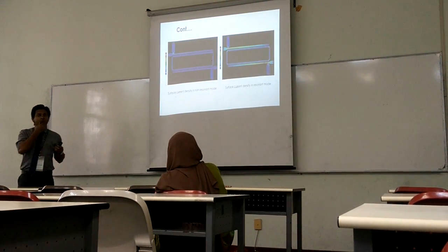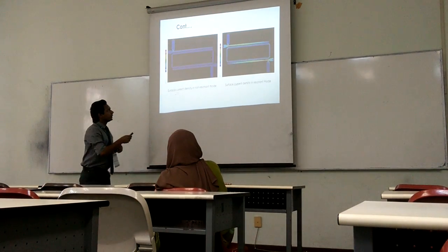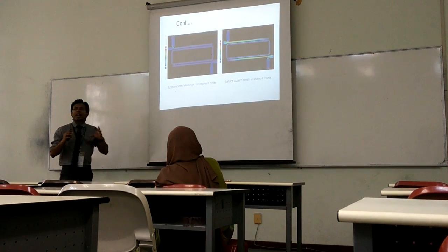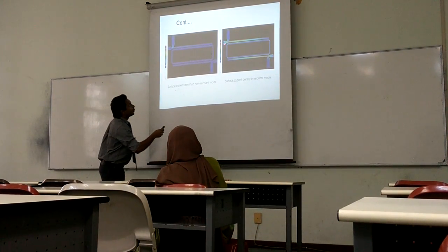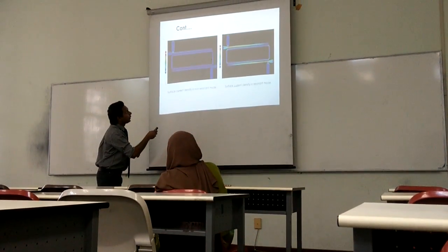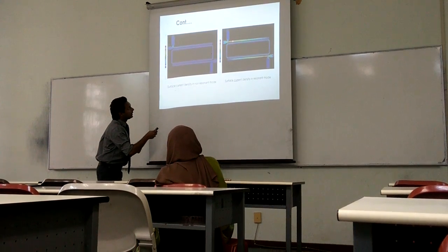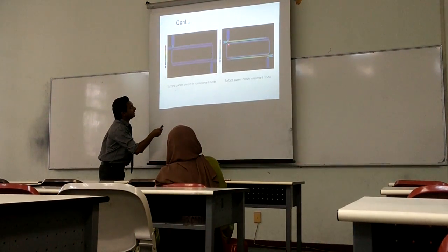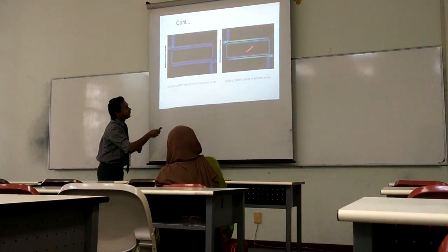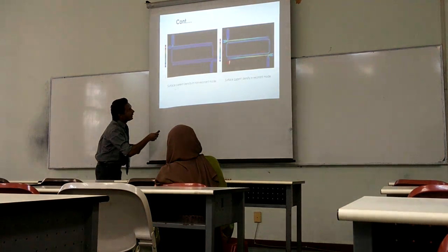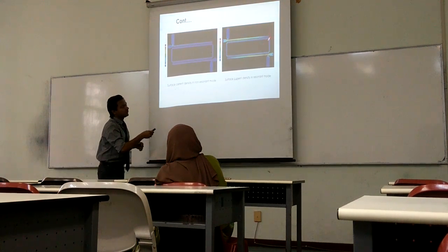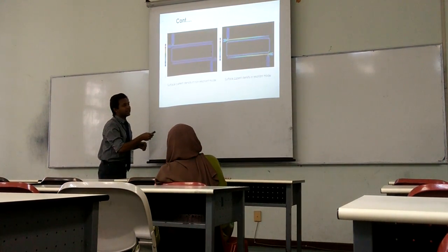And let's look at this one. This is interesting. I wish I could show you the video, but anyways, this is for the non-resonant mode. This structure actually works as a trap for electromagnetic signal because we have two short-circuited stubs and a step impedance resonator technique. So when the signal comes to port 1, you see this area becomes high with too high current density first. Then the signal comes, and then here also becomes high. So it's a kind of trapping, pumping the electromagnetic signal and releasing it on the second port.